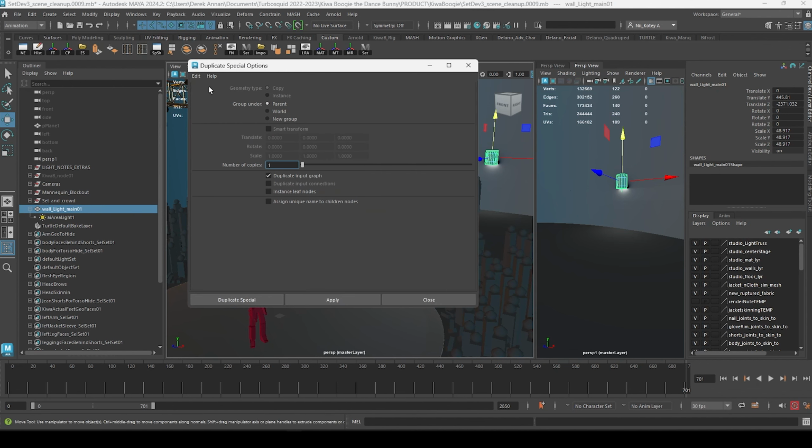So for now, I'm going to leave them like this. When I put in the other lights, I will continue to troubleshoot them, specifically their intensity or exposure. I think it's wise to use an intensity of 1 and only manipulate exposure to control these lights. So I'm going to try to do that. Make sure that my intensity is 1 and that I'm controlling through exposure. So I'll go 15, and that's what I'll be doing.